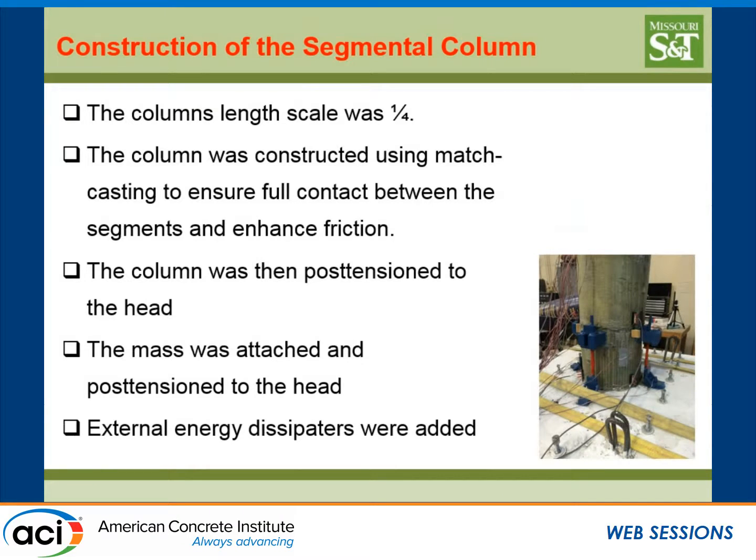And here are the energy dissipators. As I mentioned, we have number 4 bars. So these bars are on the 4 sides of the column, and they are tension-only dissipators. Just to avoid also the low cycle fatigue of the bars, we use tension-only dissipators. That means we have the bar over here, and it's connected to, as you see, a heavy angle, and we have a nut over here.